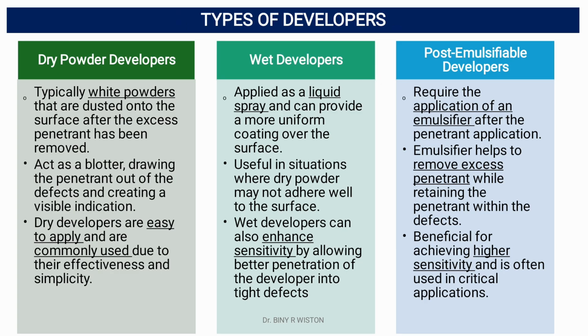Wet developers are applied as a liquid spray and can provide a more uniform coating over the surface. They are particularly useful in situations where dry powder may not adhere well to the surface. Wet developers can also enhance sensitivity by allowing better penetration of the developer into tight defects.